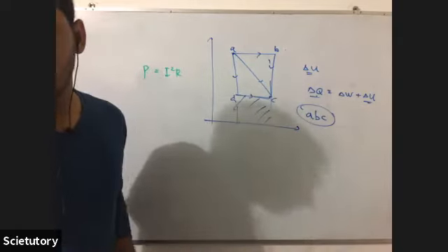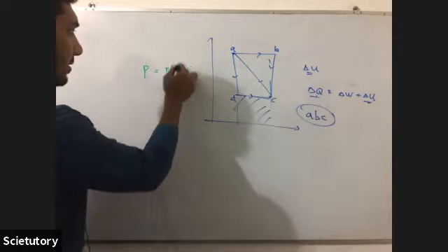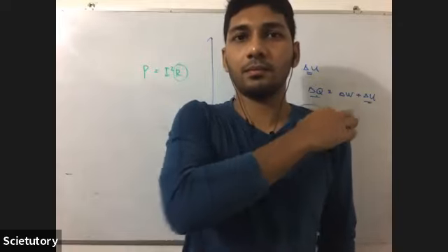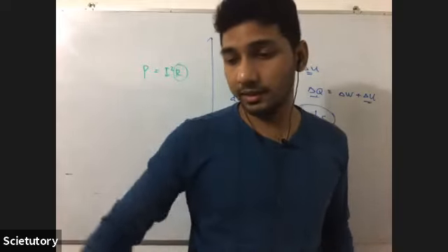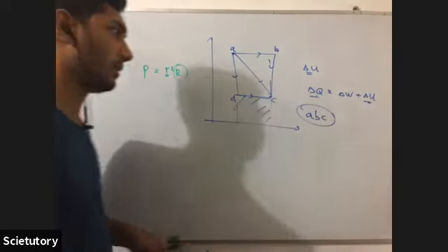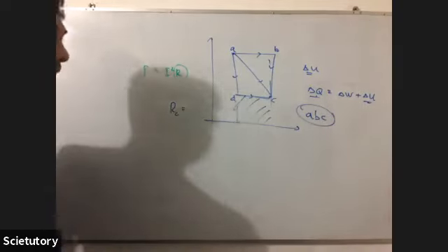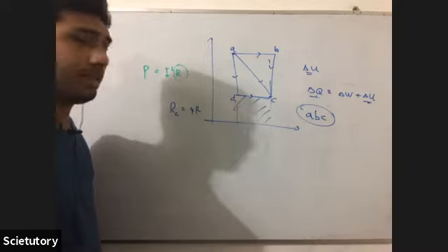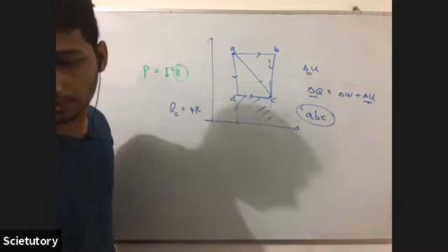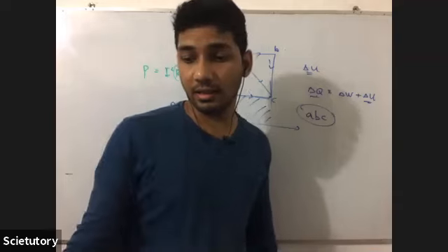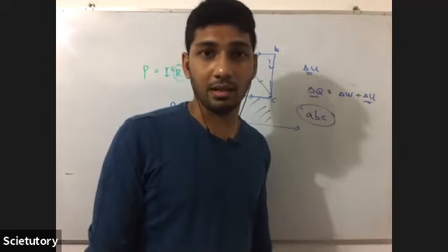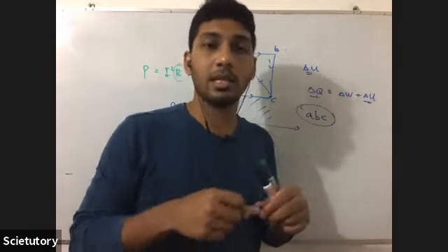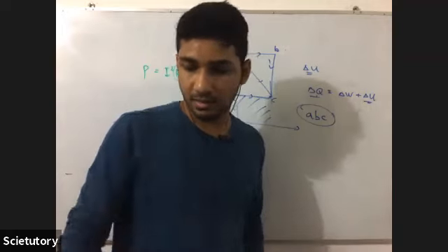So we have to think about R. Which network seems to have the highest R? C, because the resistors are connected serially. If we say the equivalent for C is RC, it is 4R. For B, the equivalent will be less than R because the rest of the system is connected parallel to the first resistor.